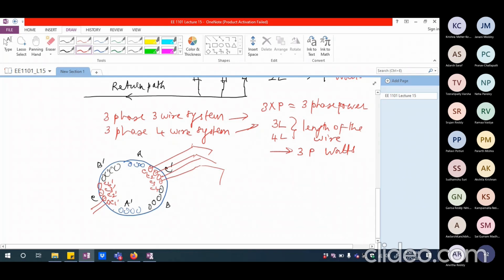Okay. So this is basically the importance or the significance of 3-phase system. The 2 major portions are, one is you will save on the copper for the same amount of power being transmitted, and the second one is there is no oscillatory torque or oscillatory speed. So the vibrations in the shafts are decreased.